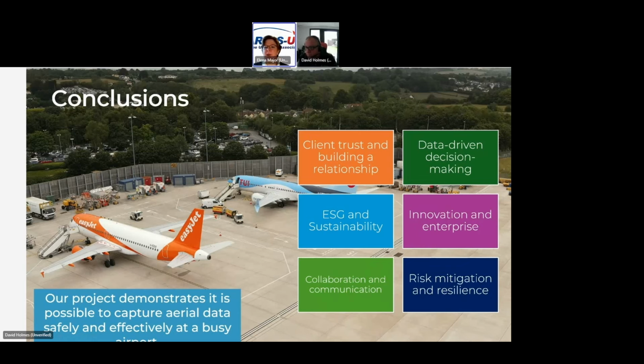What other outputs can be produced from the data capture? Okay, so once we've got the point cloud, which is the basis of the data we would have for this, it's possible if you wanted to do a BIM model or other aspects of 2D CAD from it. The same data could go into GIS, so you could have an orthomosaic in a GIS platform with your terrain data, so digital terrain model or digital surface model as well. So once you've got that point cloud data, there's lots of other applications that spin across from AutoCAD into GIS as well.